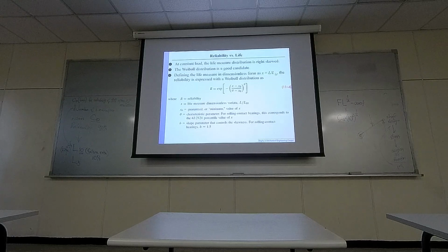So in our category, in the manufacturer's category, usually life for 90% is 10 to the power of 6 revolutions. Okay, so you can have any amount of life, so it's going to be normalized as a value x. So you will have some reference number x0 and some parameters. This is basically describing the shape. Theta and b describe the shape of this exponential function.